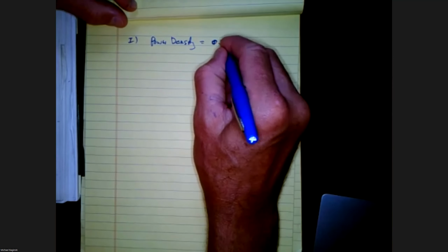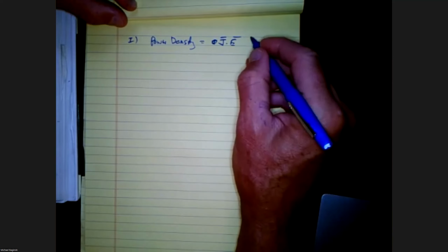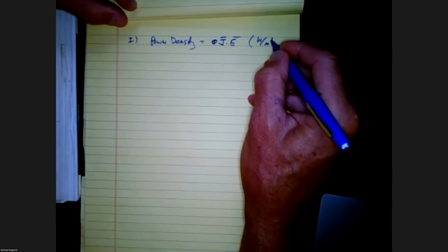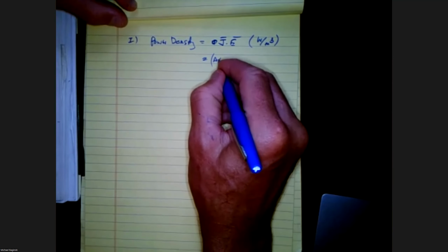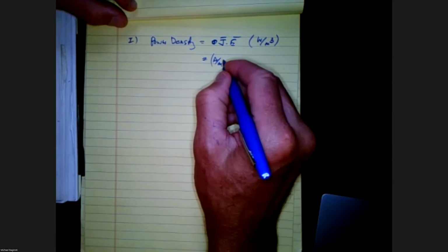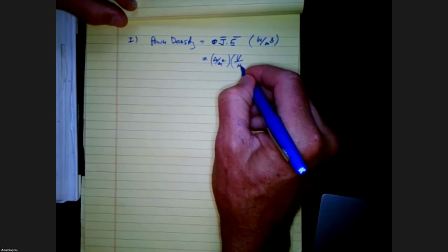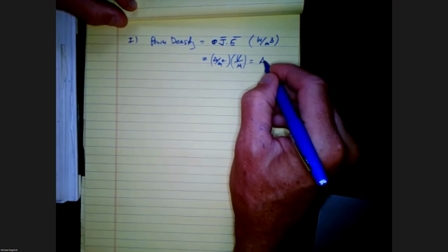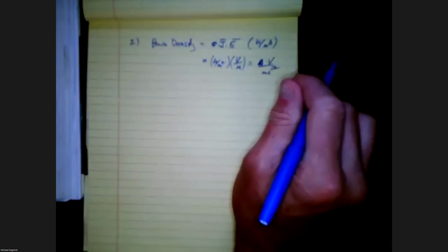It's really J times E, if you do it this way. If you look at the units, they will be watts per meter cubed. J has units of amps per meter squared, and E has units of volts per meter. So you get amp volts per meter squared, and amp volt is a watt. Y'all agree with that, class?